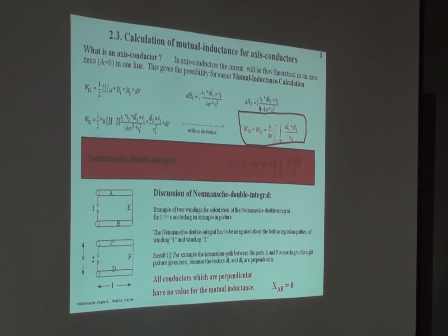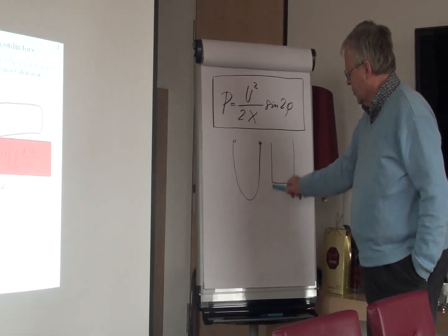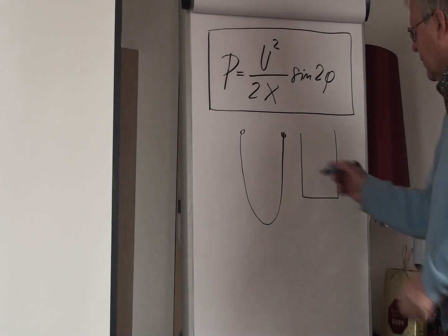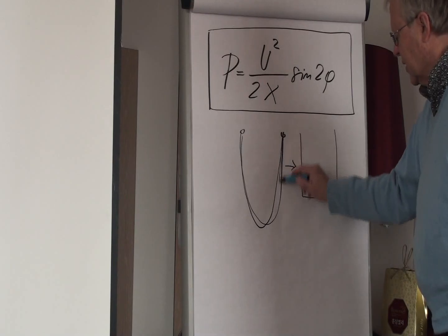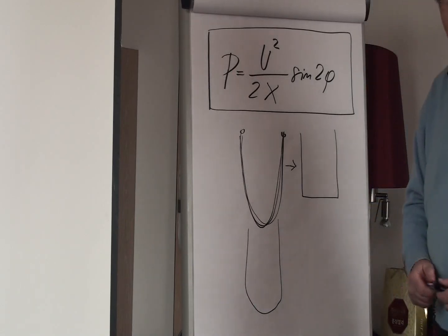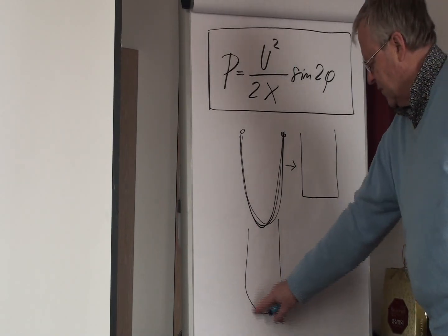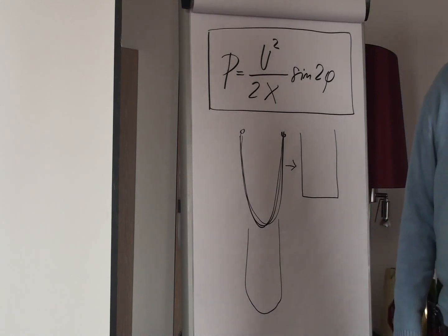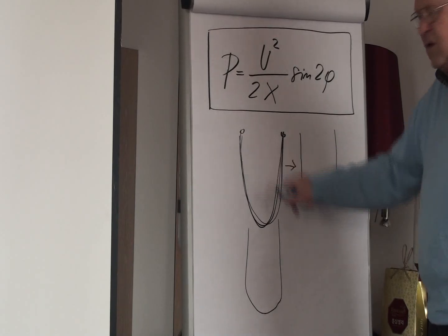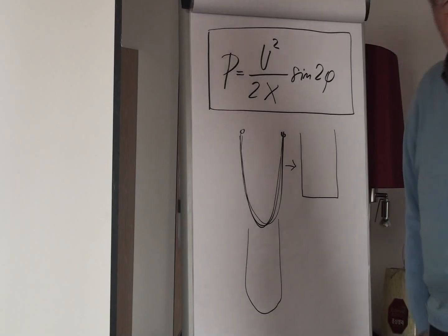Also the flexible cables. There's an equation for this, but we say it's the same length. This is for making an easier calculation, because there's no mutual inductance between these vertical and horizontal parts. There's also a special equation for this, but in most cases this is like a half circle, because of the flexibility of the cables. The difference between this and this is small. We neglect that.